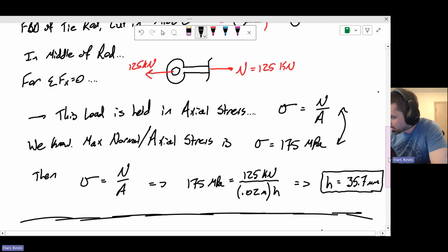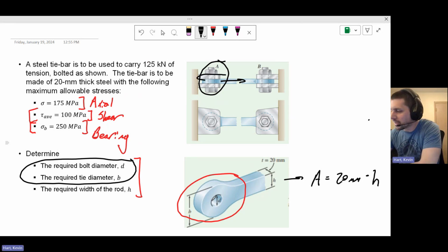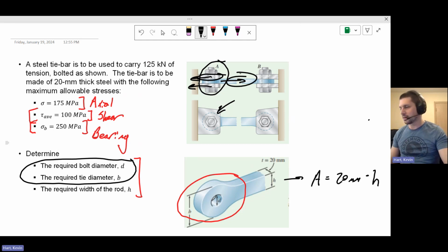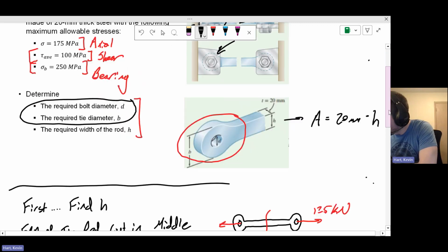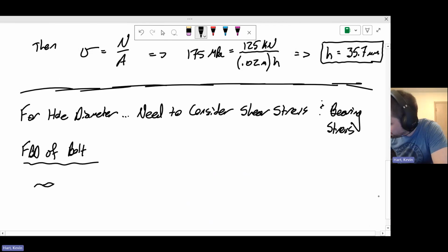In this case, we have the bolt here at A, and it's being pulled by the tie rod. And this little gray flange is resisting, in double shear, the load that we're applying, which is our 125 kilonewtons on that pin. So if we look at what that bolt looks like, it's going to look a bit like this. Here's a section of my bolt.